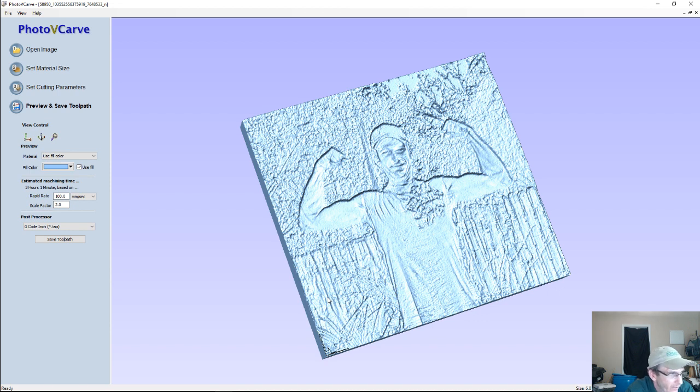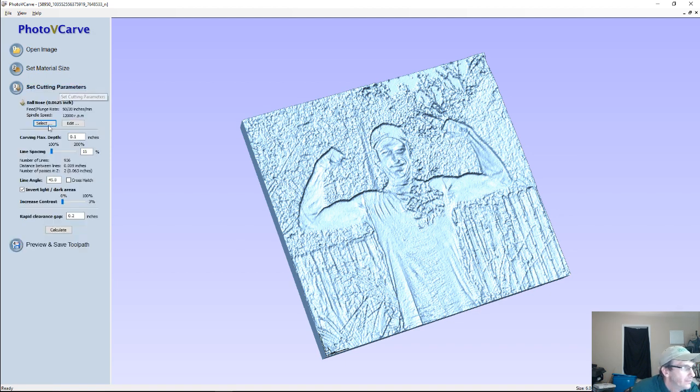I have an issue with the V-Carve part of it. But the lithophanes, I've never had an issue. Really, really good stuff. And these parameters, 0.1, 15 on the finish cut, 45 degree, 0.2, invert your color. They're pretty much my defaults. And guess where I got them from? From the instruction manual that came with the software. I've never had any reason to vary from it because I've gotten near excellent results every time.